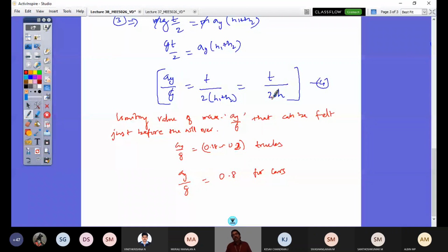But the CG location in a vehicle is at an elevated position from the ground, generally a high height in trucks or SUVs. Whereas in race cars, you see that the height of the vehicle itself is very small. So there, unless it is very hard cornering, the vehicle has an oversteer tendency. Your roll moment distribution is more on the rear axle than on the front axle in race cars.